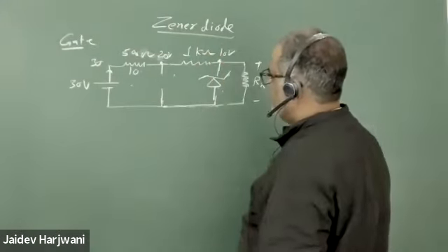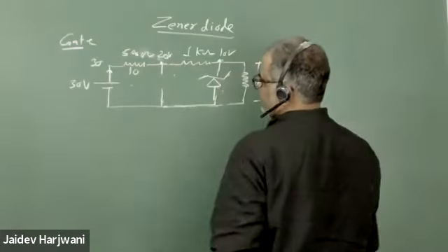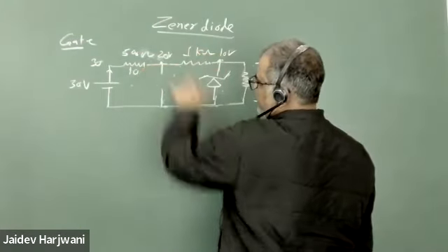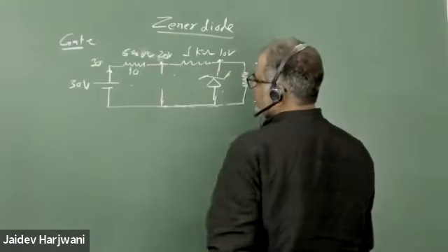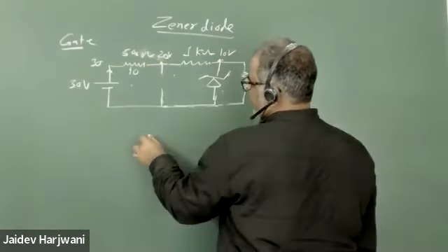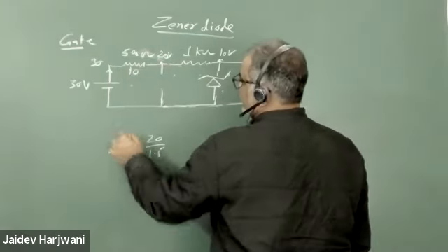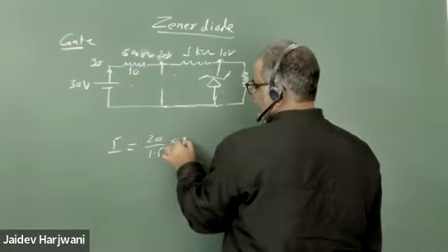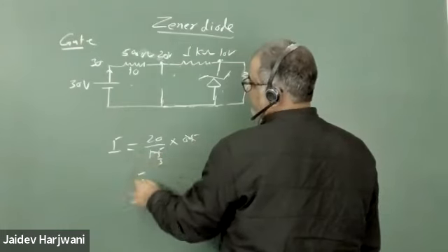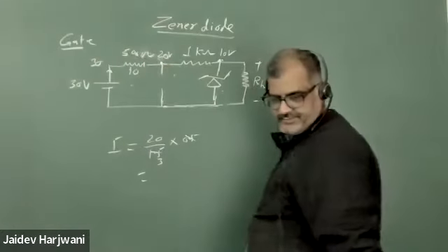Now again the current is coming here. Here 10 volts, so this means 20 should be here. You can check how much is coming here: 20. If 20 is getting here, the current will be 20 divided by 1.5 kilo ohm. Now how much loss is across the 500 ohm, 0.5 kilo ohm? You can check, some 6 volts will be lost here. So the remaining 30 minus 6, 26, will come here.